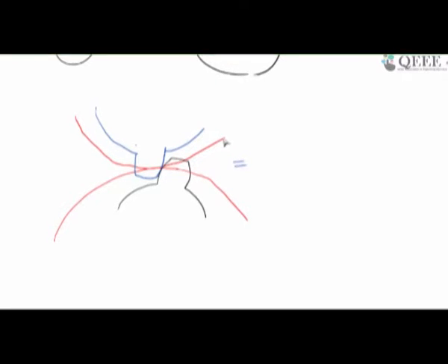So, associated with each gear, basically embedded in the idea of gear is the idea of friction disc. Whatever motion that the gear pair is transmitting, we would like to visualize that as an equivalent motion between the two friction discs, and the associated geometry of the friction disc will then become our pitch circle, right.